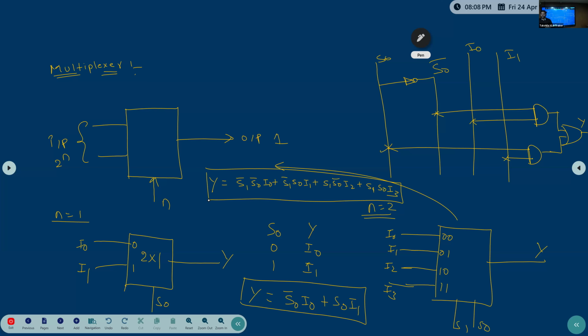There they will add extra logic to enhance the performance. Sometimes the enhancement does not come from the RTL itself when you are exiting the chip. Then they will say we need to add some more logic here to enhance the performance. They know that at the end they will add some logic, so at the start itself they will add some spare cells.